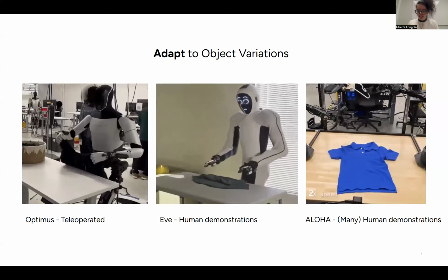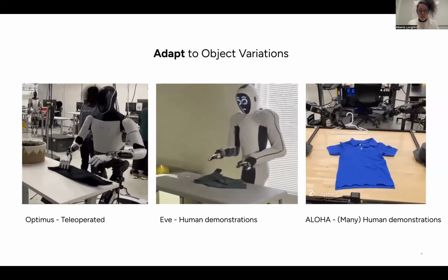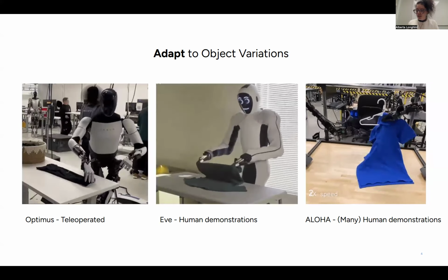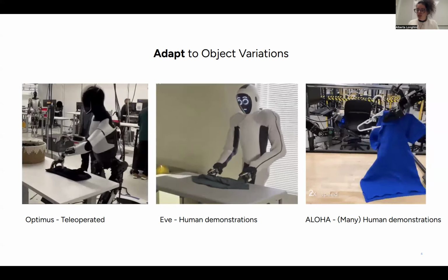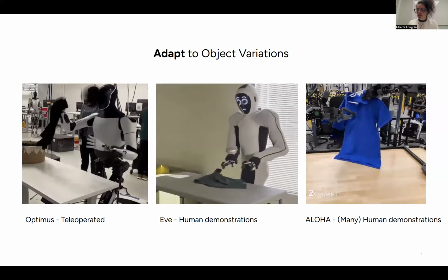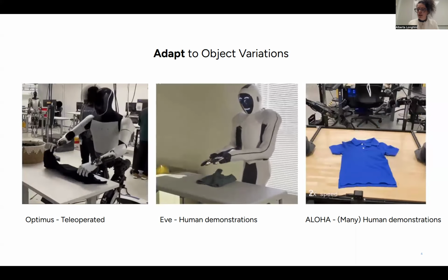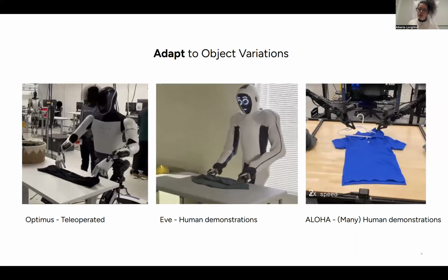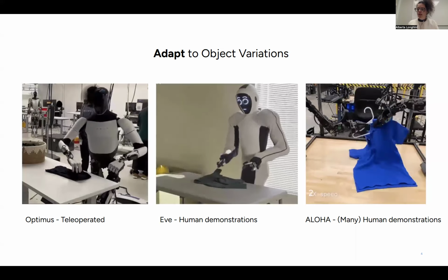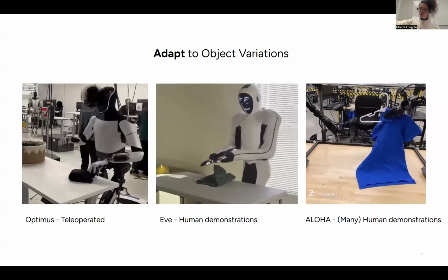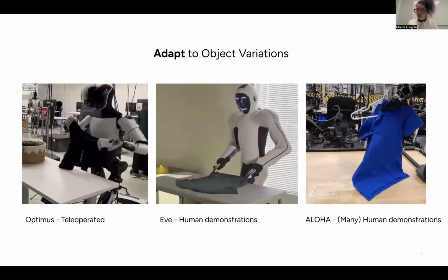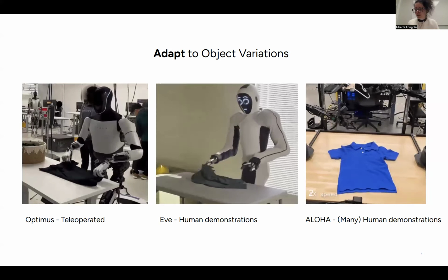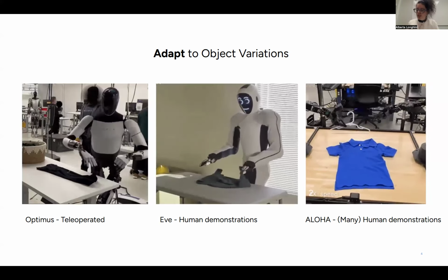Or, for example, I can think of when you want to spread bed sheets. You can do it with quasi-static manipulation, but in the end, dynamic manipulation is more efficient. It allows you, for example, to reach better your space, because you don't need to reach all the points, but you can use the dynamics of your cloth to reach further points in the cloth. While with quasi-static, you really have the robot to reach some corners. So I think that dynamic manipulation extends the reachable space in the end.